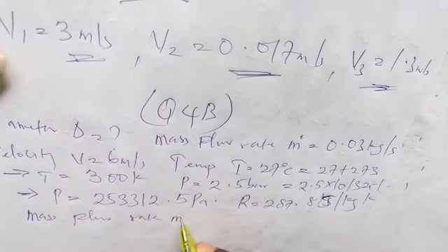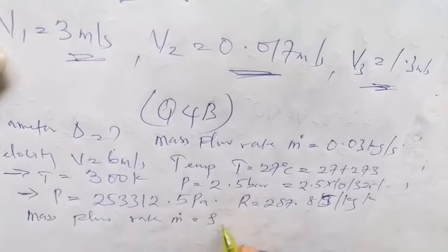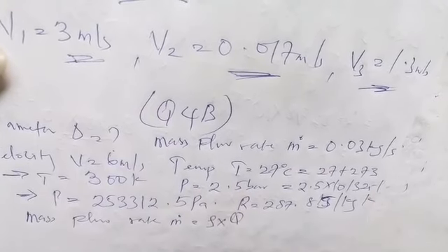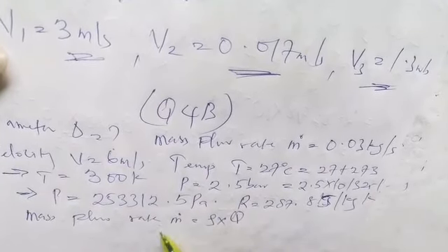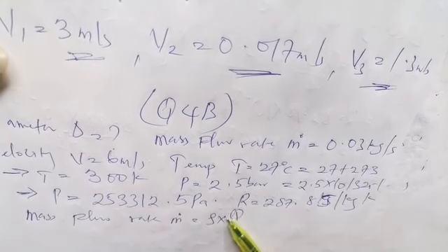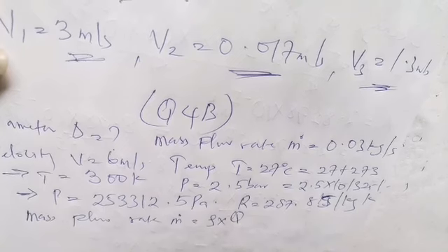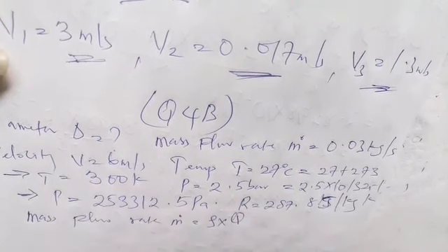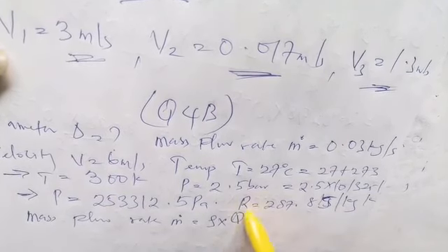m dot, is actually density times discharge. So it means that we know the mass flow rate. All we need to do is find the density of this fluid, then solve for the discharge from the formula. If we can find discharge, then velocity was given to us, which means we can find area. From there, we can find the diameter of the pipe. So our interest now is to find discharge.